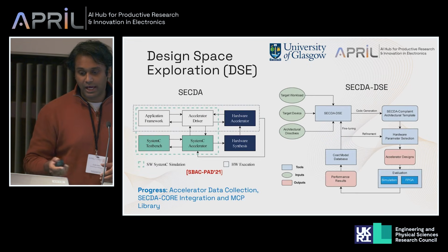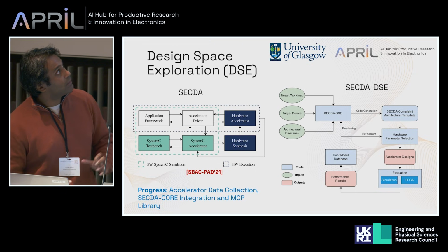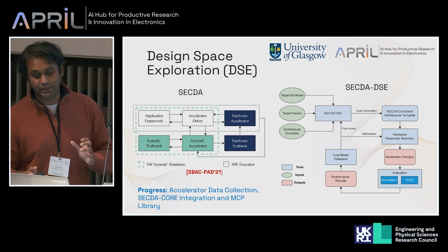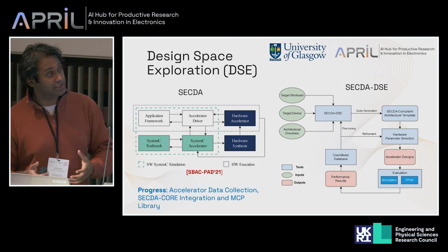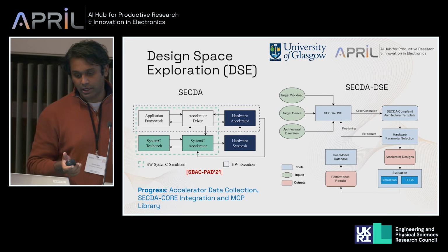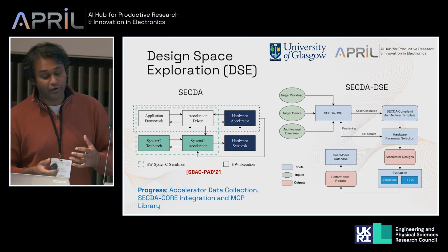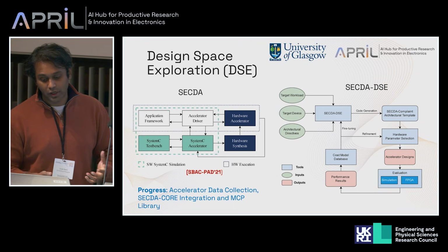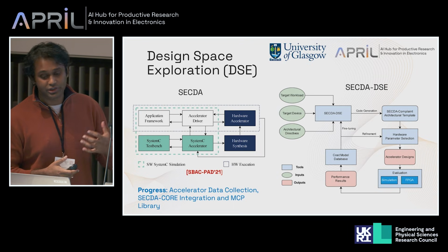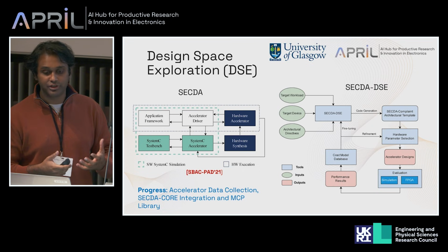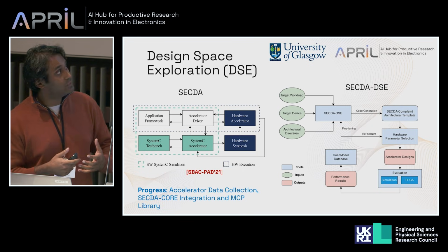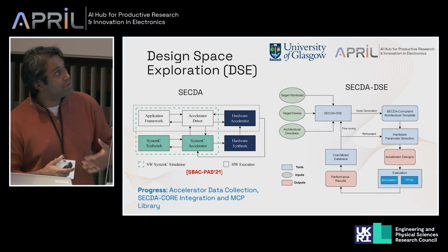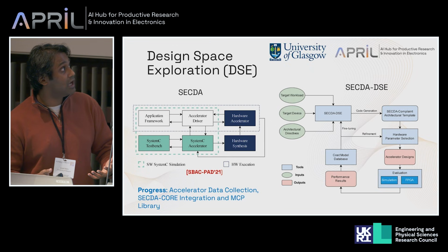So with that, I briefly present what the hardware software design methodology is on the left, and then what we do in this project, the SECDA-DSE. To quickly cover the SECDA methodology, it requires two design loops. One is based on SystemC simulation. SystemC is a hardware description language and also a simulation language. Through this, we can quickly iterate over many designs without ever having to do hardware synthesis or logic synthesis.